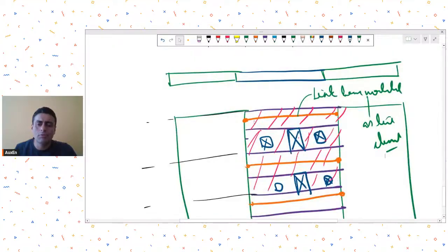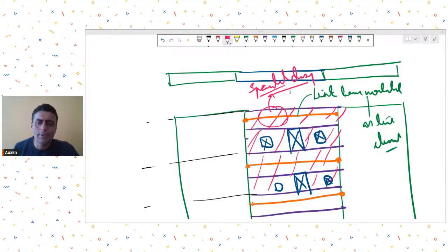Second problem is when you model your spandrels as shell elements, actually there is some error that ETABS commits in the spandrel design. So I have checked it myself. The lever arm that ETABS is taking when we make shell elements and assign them as spandrels, there is some mismatch in the ETABS outputs, especially because it takes the lever arm of that deep beam incorrectly.